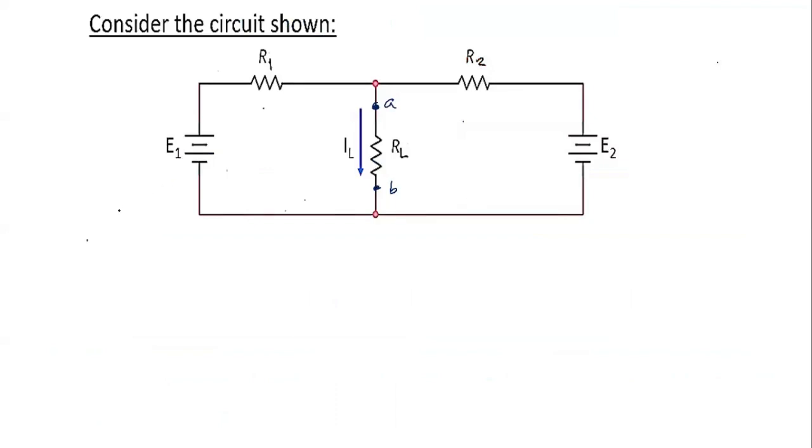So step 1, solve the RTH value, excluding the value of the RL. So let's remove it. We have the terminals A, B where the RL is connected, so we have to remove the RL here. And then we connect back the R1, and the source voltage is replaced by a short circuit. That is how we set the voltage source to 0.